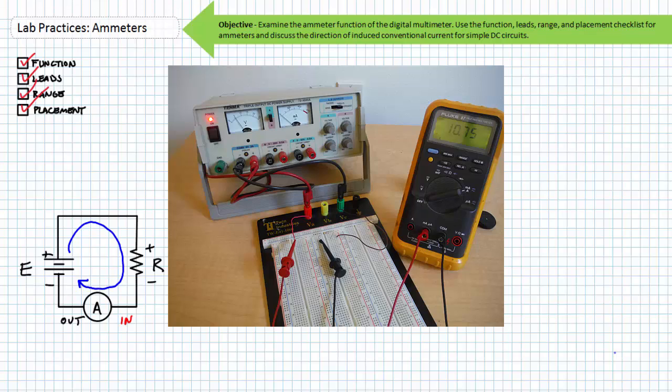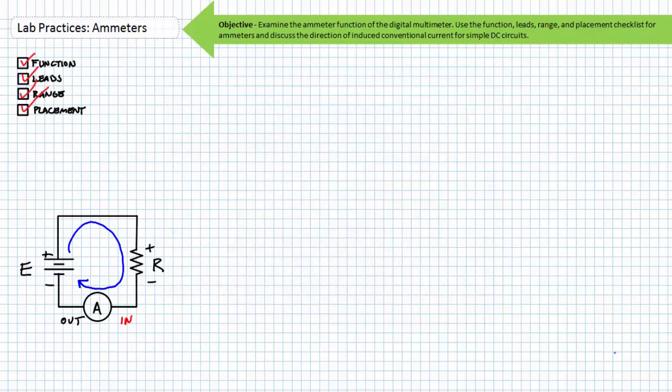The microampere mode is for especially small current measurements and uses this same lead input. I'll admit this intermixing of function, leads, and range is a little confusing for the Fluke 87, but this is where familiarity with your specific DMM pays major rewards.